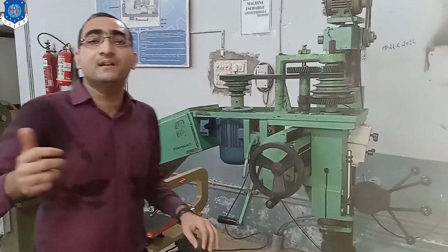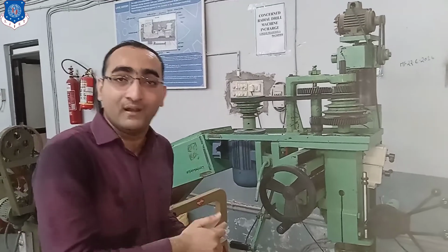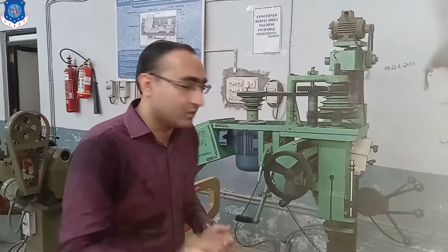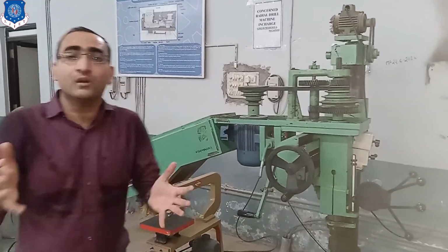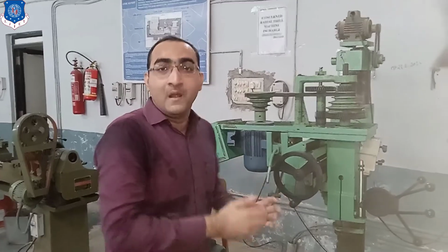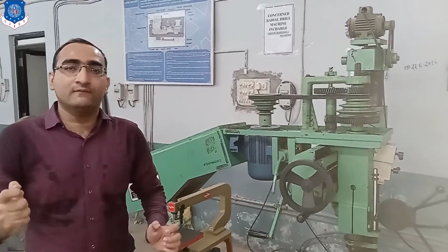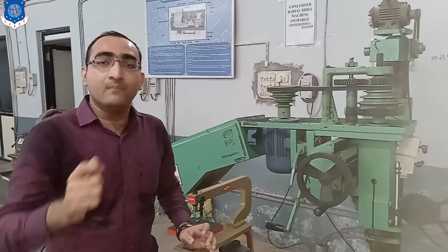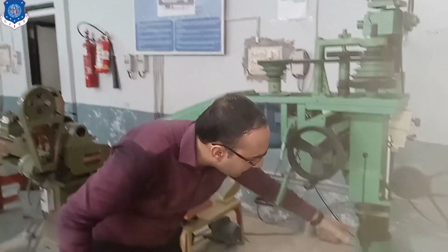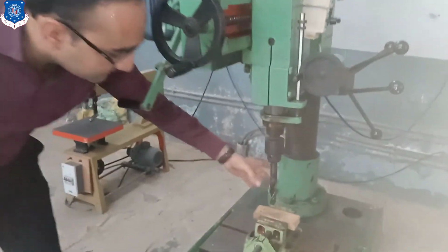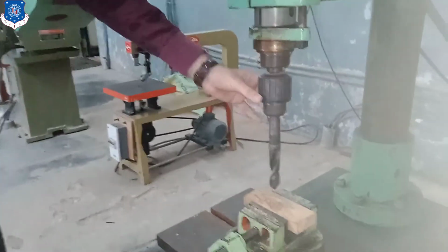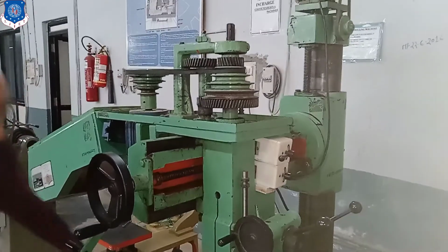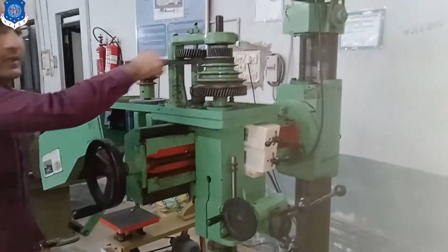That is why it is known as a radial drilling machine, because this machine gives you movement in any direction: horizontal, vertical, and then circular. So 360 degrees, wherever your component is, you can go for it. The highest capacity of drilling can be given with the help of this. Holes of 1 to 35 mm diameter can be generated with this drill bit. The drill bit is held in the chuck, and this chuck is fitted to the drilling head, and the motion to this tool is given by this.